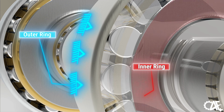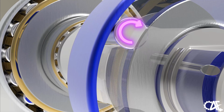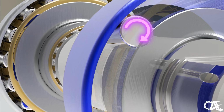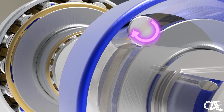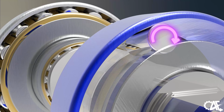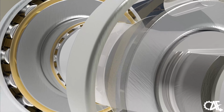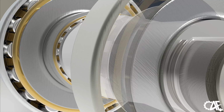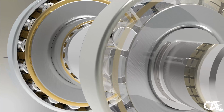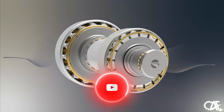As the inner ring begins to rotate clockwise, it imparts a tangential velocity to the roller. This means that the surface of the roller in contact with the inner ring receives a certain speed in the opposite direction. This is due to the friction between the roller and the inner ring surface. Since the outer ring is stationary, one side of the roller remains in contact with it, both preventing any rotational motion and initiating the roller's roll along the interface between the inner and outer rings.